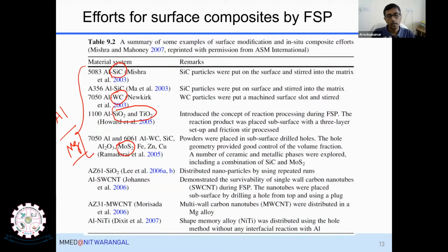People are using it, and the cost of just one boron nitride tool is around 16 lakhs. Whereas if you want to process aluminium, magnesium, zinc, some soft materials and their alloys, they can be easily processed using an H13 steel tool. The typical tool steel is good enough for these materials. Hence, plenty of work is focused on processing aluminium or magnesium.